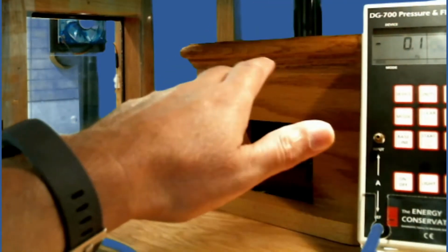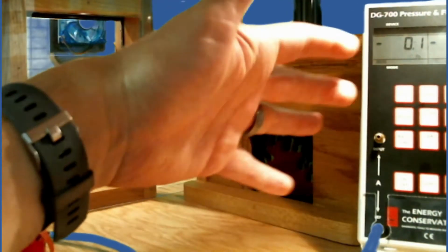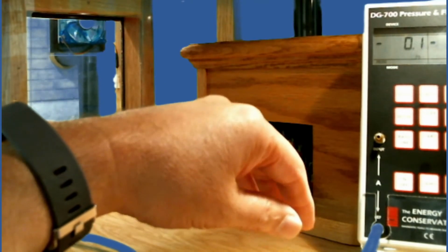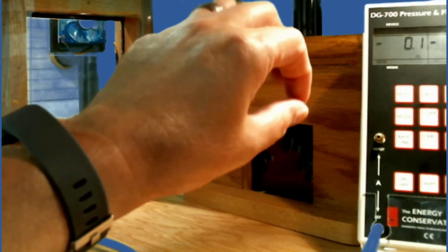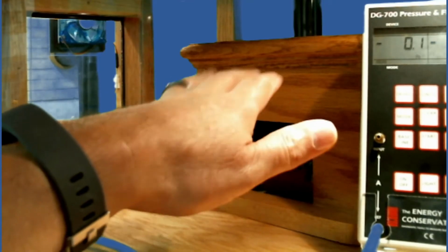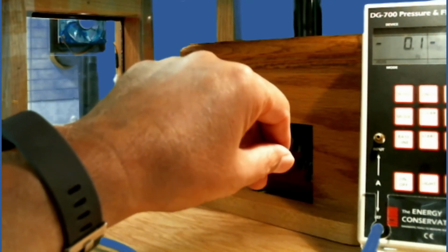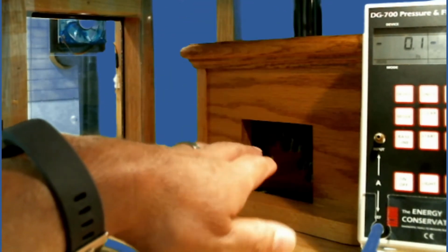So what you would do is take your manometer, if you can physically be in the room with the CAZ, your combustion appliance, and you just run this hose to the outside. You can run it back through the house and out the blower door, or you could run it out a crack in the window, or use a little probe. You want to make sure you can shut the window or exterior door back. You don't want to leave it open or cracked. You want it closed.